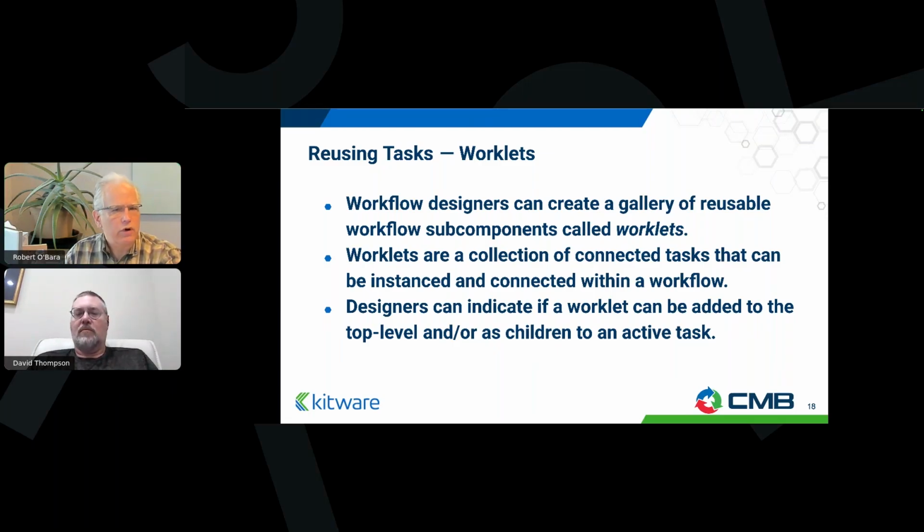Whether that's at the top level of a workflow or inside a task, say I'm going to generate a volume mesh. Well, you open that up, maybe I'll have a snappyHexMesh child and a merge mesh child and so forth in there. It allows you to reuse things. Workflows themselves are connected, so they've already been pre-wired in those cases. And as before, a designer can indicate whether or not a worklet can be added to the top level, or if this workflow, worklet, or active task has these characteristics, then it can accept these types of worklets to be dropped into them.